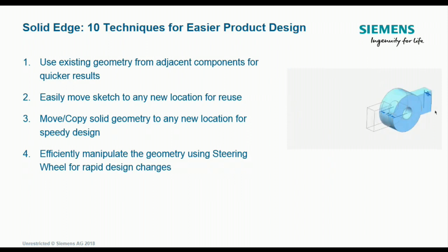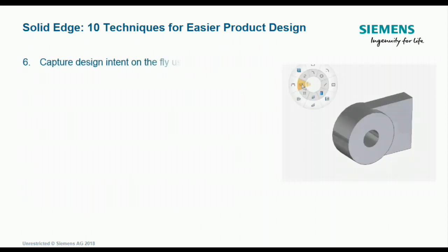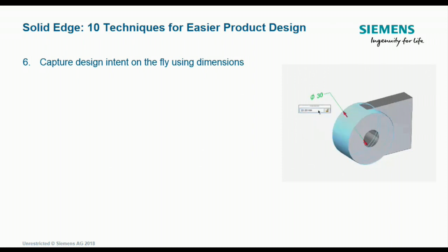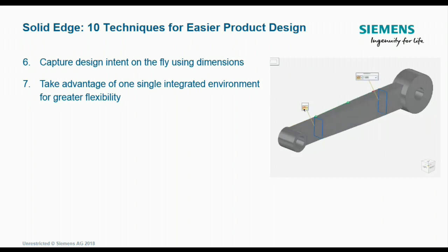It works the same way on imported geometry, providing unmatched capabilities for working with suppliers' or customers' data from a different CAD package. Intuitively constrain 3D geometry using face relationships even on imported unparameterized bodies. Capture design intent on the fly using dimensions, bypassing the middleman sketch. Take advantage of one single integrated environment, combining direct model interaction with fully parametric features for greater flexibility.